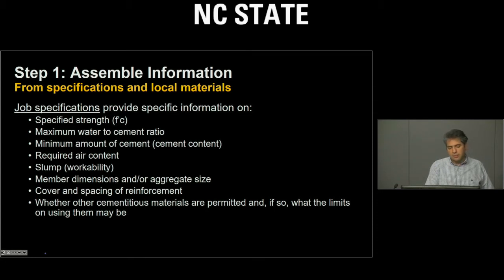What is the specified slump or workability? What are the dimensions of the members that we are casting, and what is the cover and spacing of the reinforcement, and so forth, that you will see in a second. All of this becomes very important in selecting the maximum aggregate size.